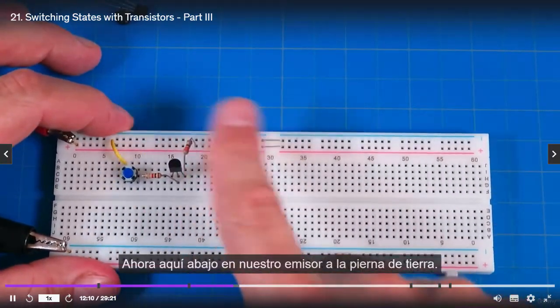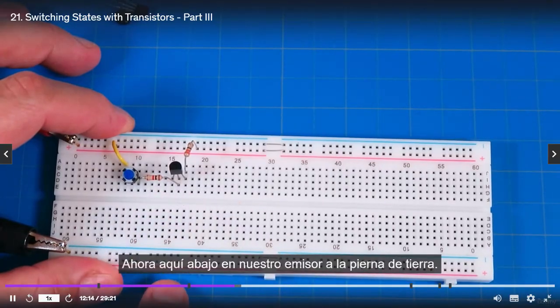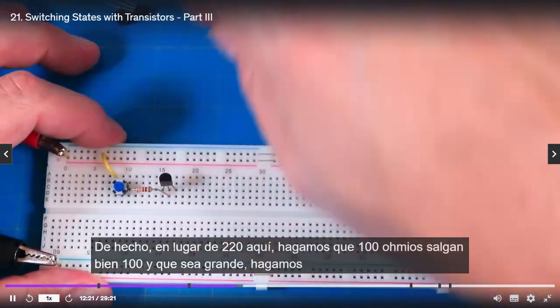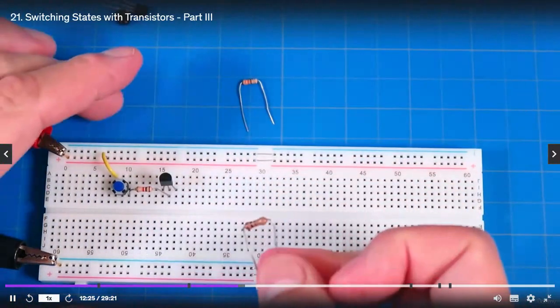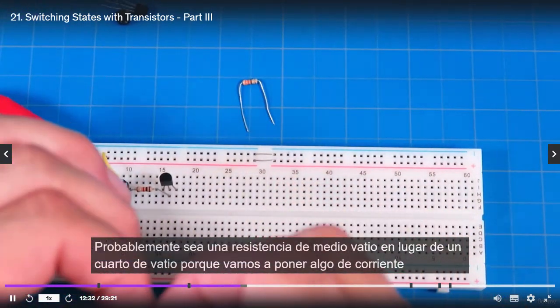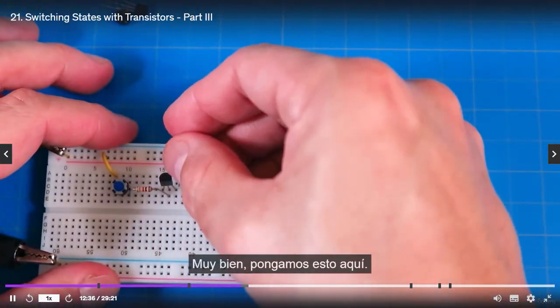Now down here in our emitter to ground leg, instead of 220, let's make that a 100 ohm, this big 100 ohm, brown, black, brown. This is probably a half watt resistor instead of a quarter watt, because we're going to put some current through here. So let's put this right here.